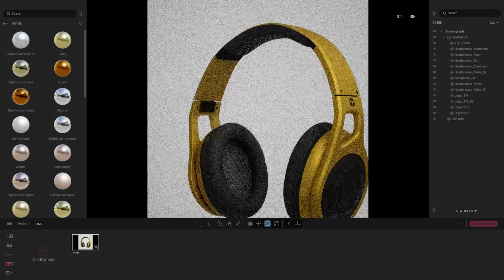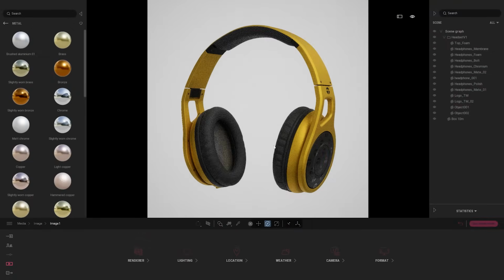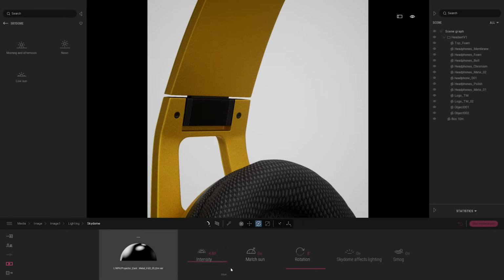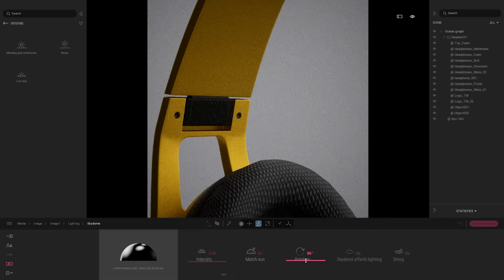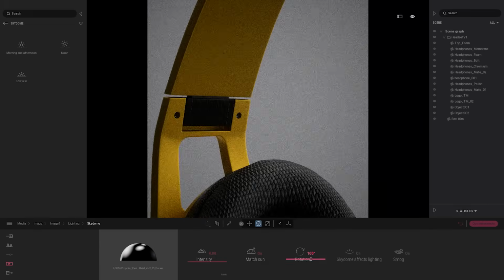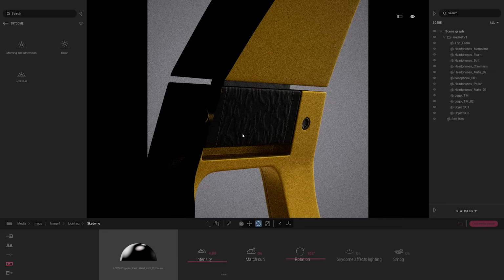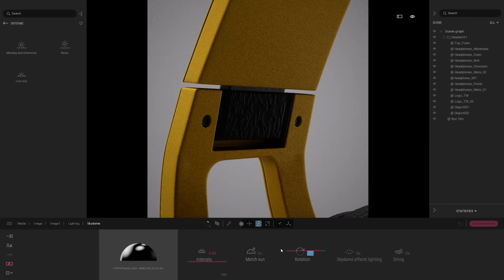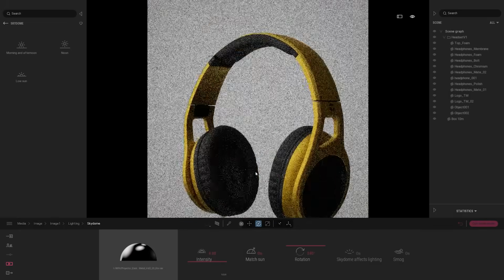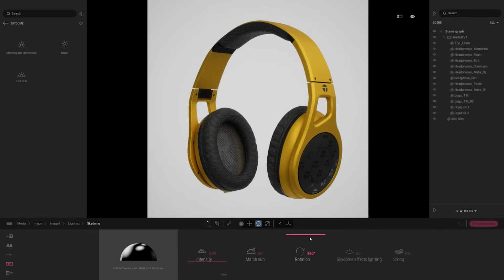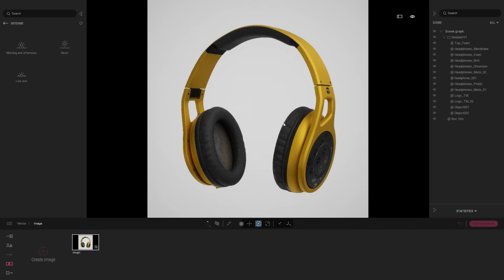What I wanted to show you with the plastic just before is that you can quickly change the lighting by turning the HDRI. So here, if I enter my Sky Dome option, I can just turn the position of my HDRI, which will allow me to see my object in different lighting conditions. So here, for example, we can see a bit better the shape and the grain of the plastic. So, coming back to our image, that should be the final image for that headset.